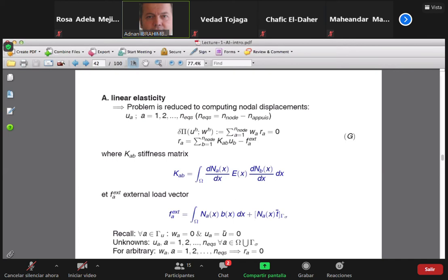So this F, on the other hand, is the so-called equivalent nodal load. Please note that it does have a dimension of the loading, but physically it does not represent the loading only. It represents mostly the corresponding work, that is, forces like P bar and B acting in terms of the chosen virtual displacement. So basically choosing the virtual displacement gives you the quantification of how these loads are really acting upon the structure. So it's not the same if you have one load or another load; it really gives you a different interpretation.